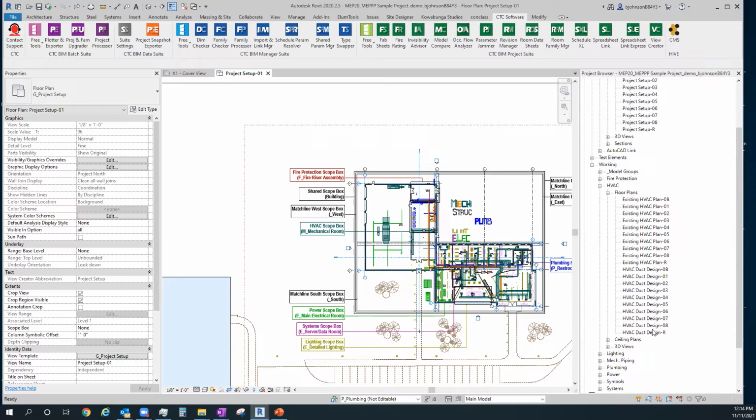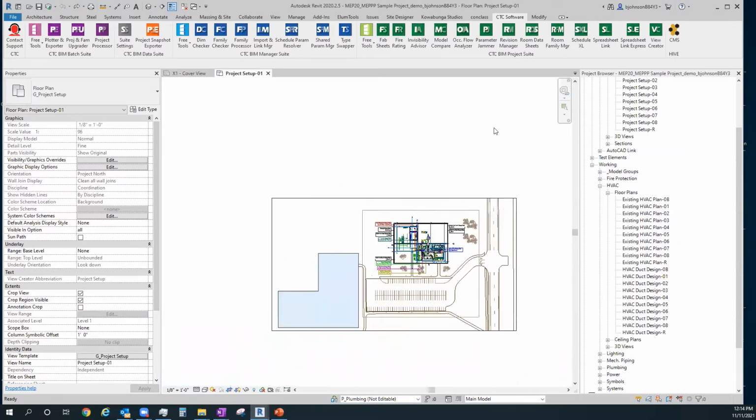I don't have the existing area views for north, south, east, and west in there, but I do have the overall plans pre-built. So whether I choose to duplicate the views and add in the area plans, or use what's existing for just a standard small building with a single footprint, I have an overall scope box for that. So if architecture comes in, say, up here, I just take the overall box and move it, and move the existing scope boxes of specific call out plans or enlarged plans over the areas that they go over, certain room types or whatnot. And then that's done.